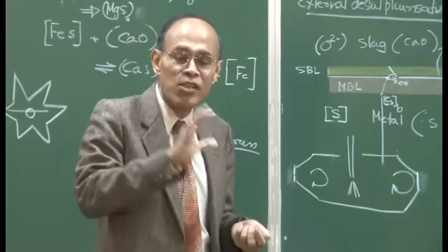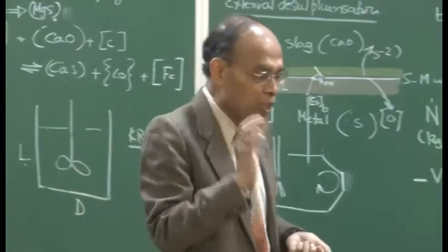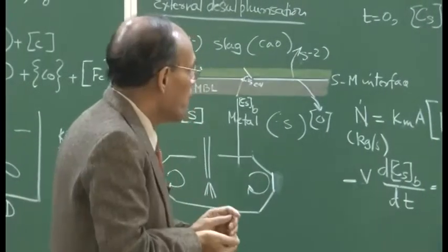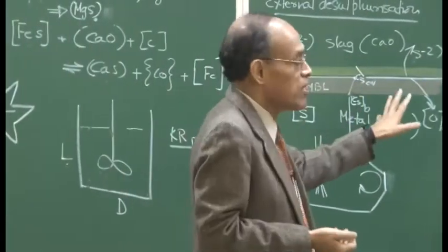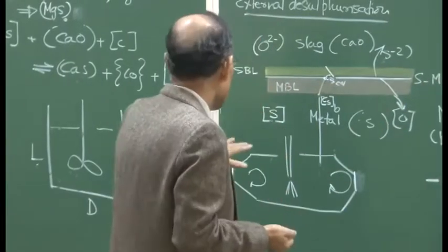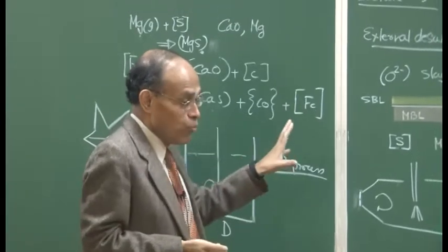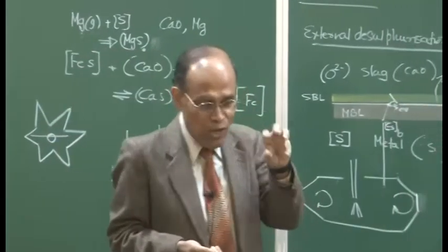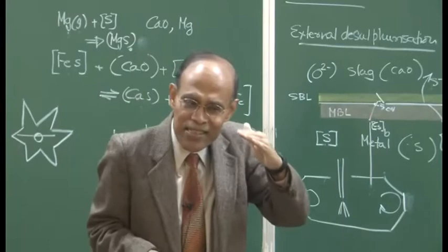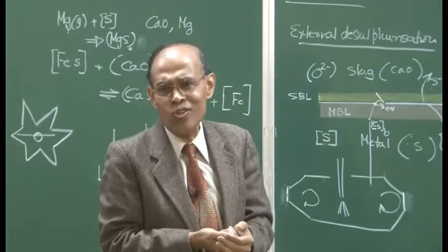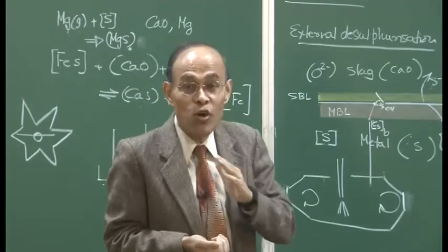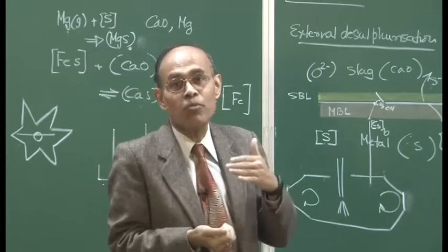But it is sufficient for us to note that as far as pretreatment of hot metal is concerned, we will be doing mostly silicon removal as well as sulfur removal. And as I have indicated, we want to have adequate silicon in the hot metal such that it is sufficient to make the steel making process autogenous. Okay? We do not need excessive silicon, we do not need too little silicon.